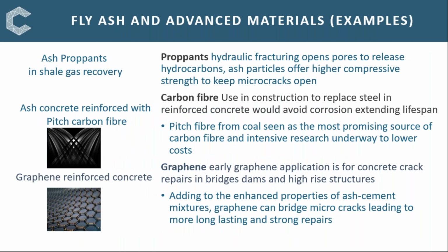Fly ash has an important application in advanced materials, and I've got a few examples here. One of the properties that makes fly ash a useful constituent when pouring concrete is that the small glassy spheres act as a lubricant, aiding the pouring of concrete. And that property is finding direct use for fly ash as a proppant in shale gas recovery. The small spheres can penetrate cracks more easily, and their high compressive strength then keeps the cracks open, allowing gas to escape. And this is already in use in projects in China.